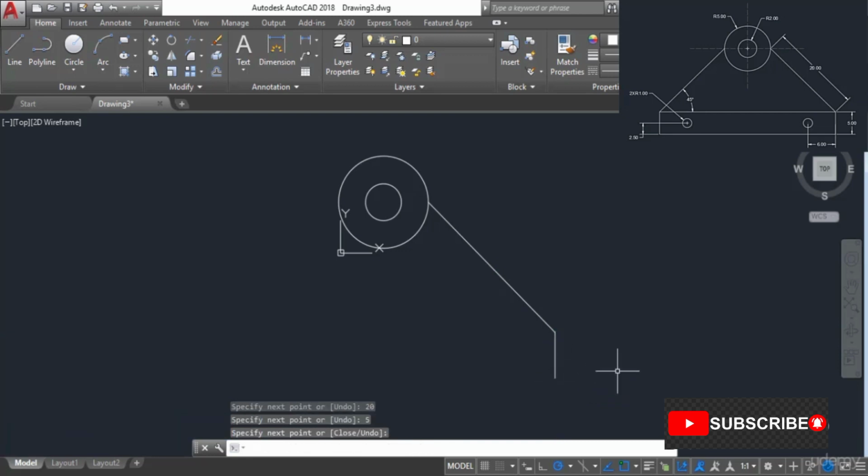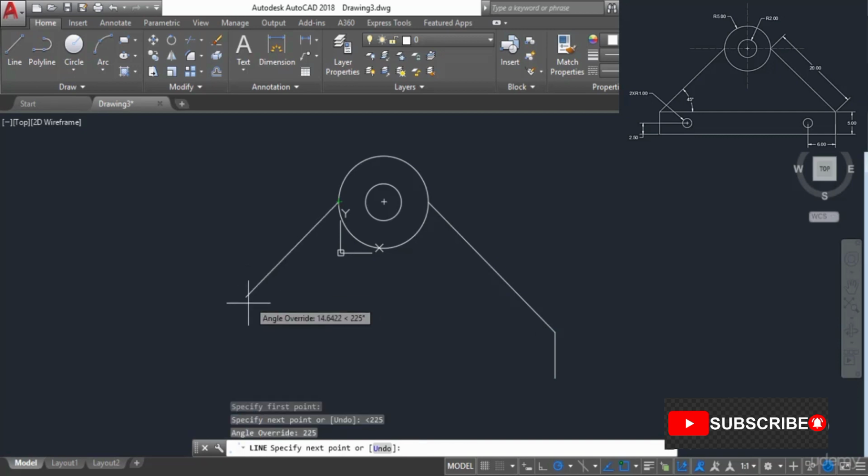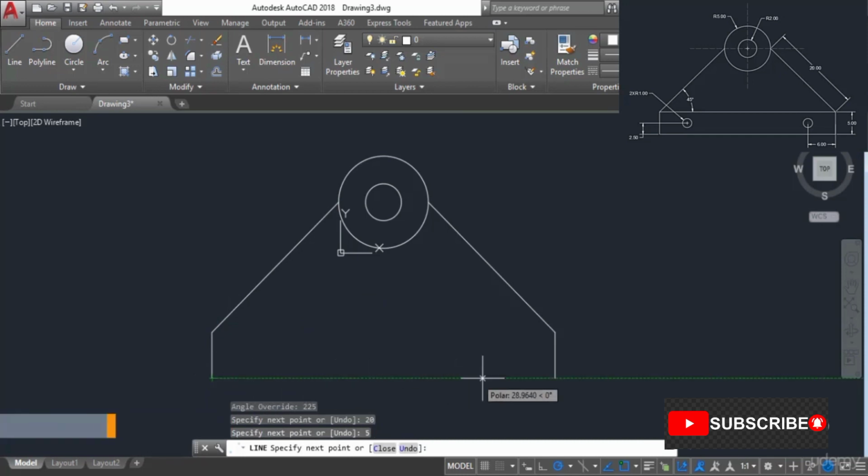Now let's press enter to exit this command and repeat the same process for the second side. So I'll press enter, I'll go to the next quadrant, and in this case I'll again type the angle sign, and now I'll type an angle of 225 degrees. So let's type 225 and press enter. So there we have it. The line is inclined at 45 degrees with respect to the horizontal line. Once again, we need to enter a length of 20 units. So type 20 and press enter. Now move downwards, enter a length of 5 and press enter. Now join it with this existing point and press enter again.